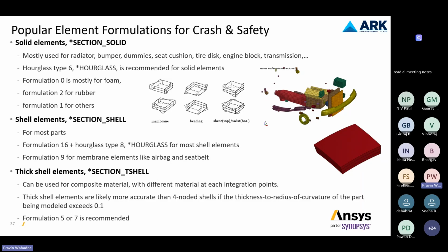In the same case, when we go with section shells, these are recommended for crash industries, and can also be used in various other simulation techniques. For shell elements, for most of the parts we generally use element formulation 16, because formulation 16 is a fully integrated element, and it has minimum hourglass, or we can say no hourglass effect.